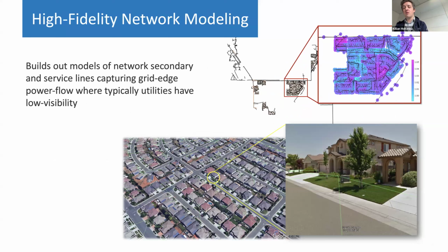One of the exciting things that we're able to validate and do with PRECISE is look at those secondary models and run those power flow scenarios to see, okay, if we just take the existing data, run power flow and see where voltages are high, does that align with where we're seeing a lot of solar? When you get high levels of solar on a network, you're injecting power that pushes up the voltage, just like if you had a water network and you started reversing the flow of water, you'd increase pressure on those pipes. So that kind of knowledge of high voltage or high pressure on a water network is pretty analogous.